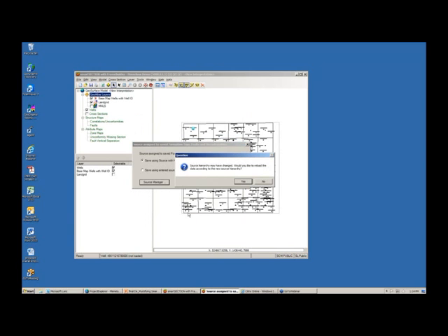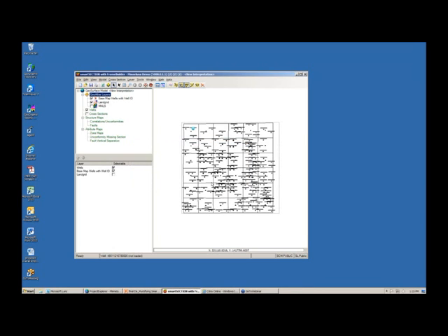I'm not going to change my source here. I'm going to leave it alone. If you are not at the top of your source manager list, I strongly recommend that you choose Save Using Entered Source. The meaning of this is that any time you actually do change a top in your cross-section, you want it to be associated to your name because you don't want to necessarily be altering somebody else's top. If you associate it to your own name, then in the Formations tab in Wellbase, you will see the original person's top and then your own still preserved. So this is a very important part of using this software. I'm just going to go ahead and cancel out since I do like my source.